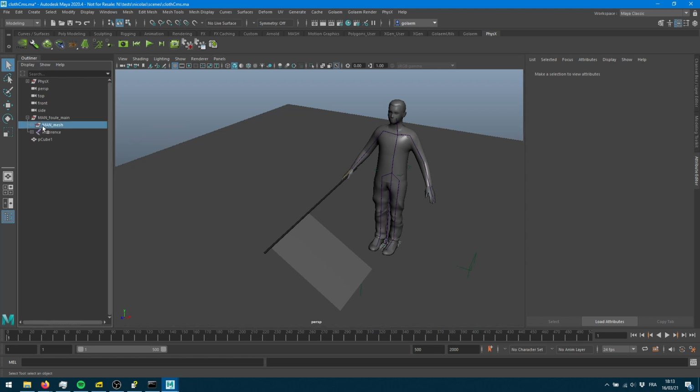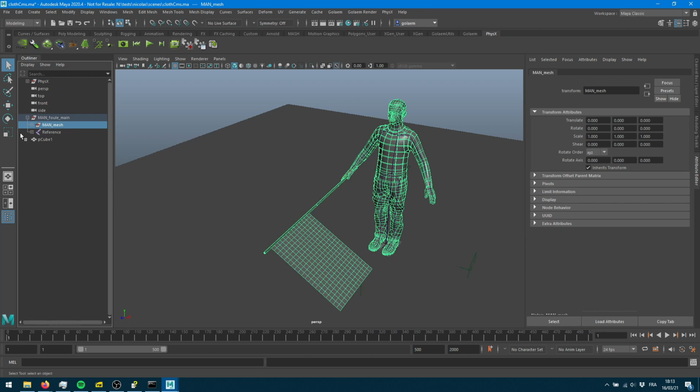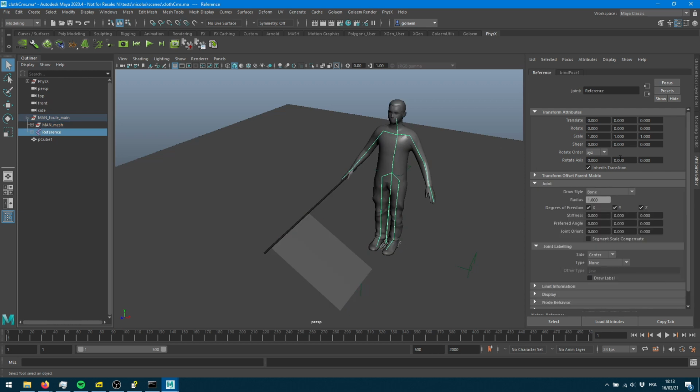I also want to provide some details regarding the setup of your character. Make sure that within your transforms, everything is scaled to 1:1:1. You don't have any non-uniform scale or non-1 scale. And also on your skeleton, make sure that everything is scaled to 1:1:1. It's really critical for the physics plugin to work properly. So here, my character's root bone is 1:1:1, and every single bone of my hierarchy is the same.